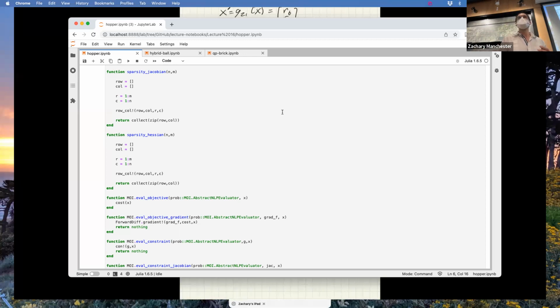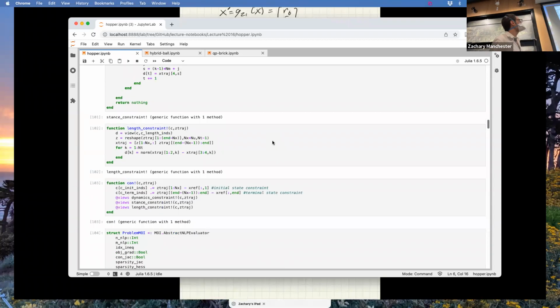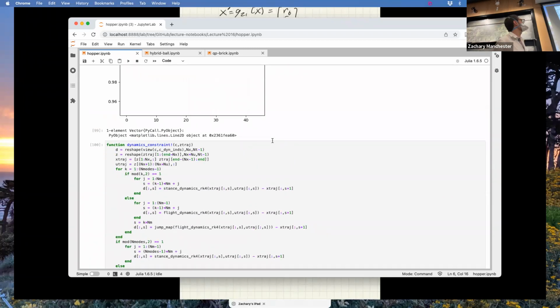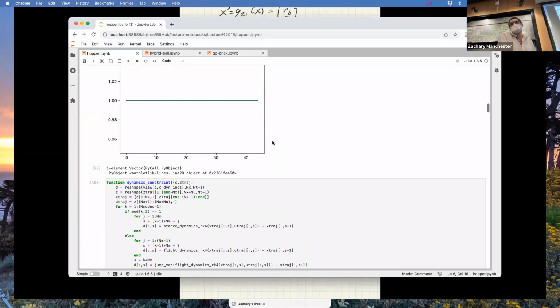Will you only constrain the body, not the foot? You just weight the cost of the foot, and the reference is on the body. That's actually kind of what I'm doing here. For the hopping reference, I was only giving that sinusoidal reference on the body, and it just figures it out. It doesn't have to be very good. It's a very cartoony thing that sort of gets it in the ballpark, and then the solver can dial it in all the way.